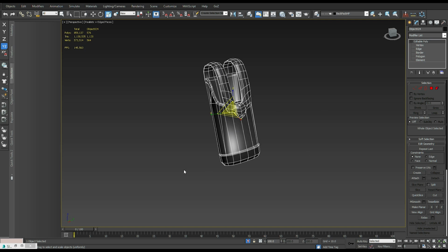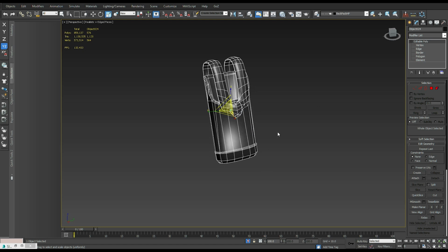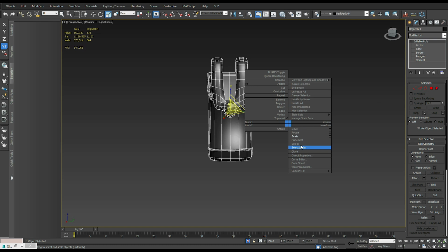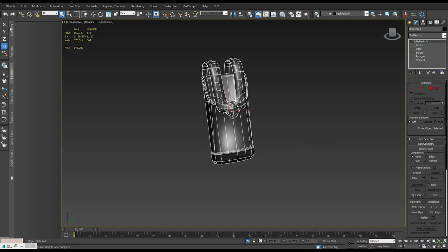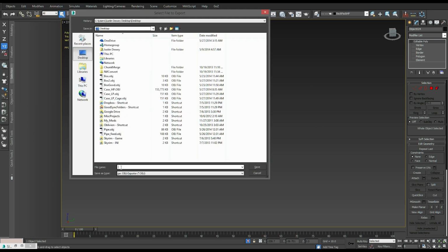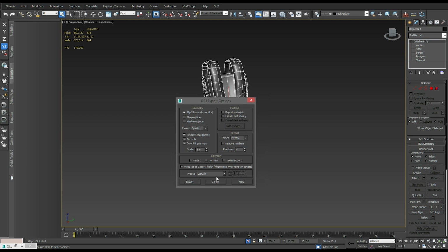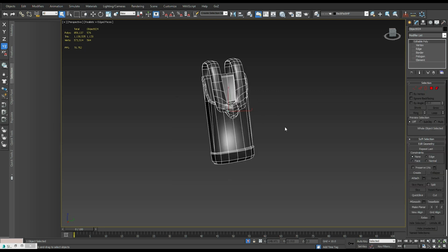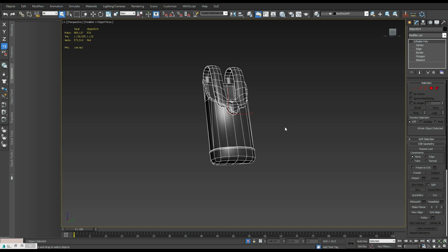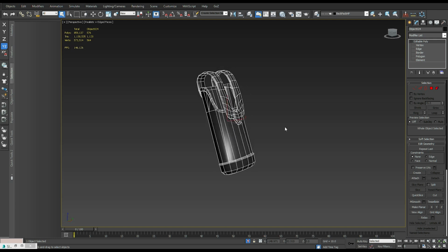If you're having rendering issues on your mesh or baking problems in Max, and you just don't know what else to do, one thing that has corrected a problem for me in the past is exporting this out as an OBJ and then re-importing it back into the scene. So you just grab onto the mesh, go to Export Selected, select a name and then Save. Now, normally when I export OBJs, I want to do normals and smoothing groups. I don't really use this optimized stuff. And as far as materials, it depends on whether you want that or not. A lot of times I won't use it, especially for just repairing something. Then we'll export that out, and re-import it back into the scene. Once again, it won't solve the problem every time, but I have had success fixing different errors on a mesh, especially going back to the spline issue. When you have flipped normals after converting a spline to an editable poly, that helped tremendously a couple times.